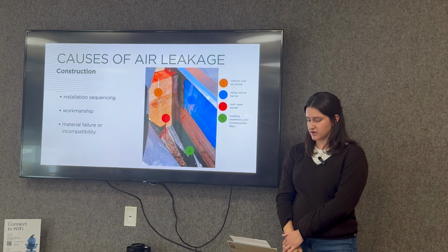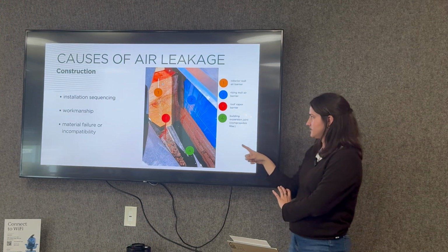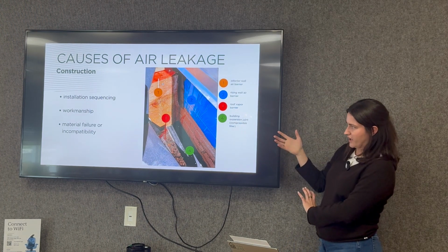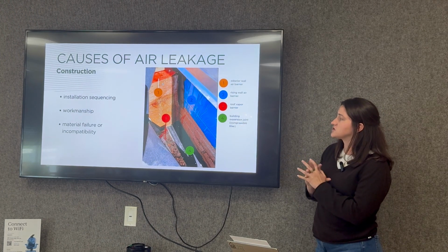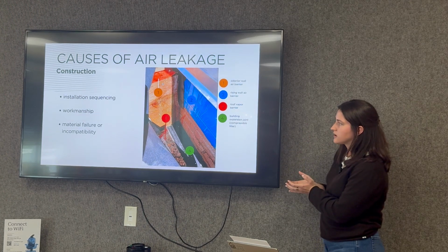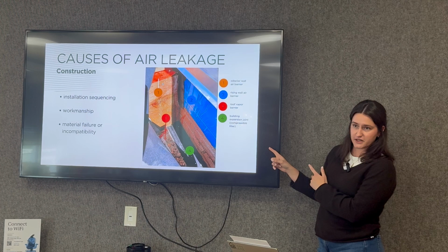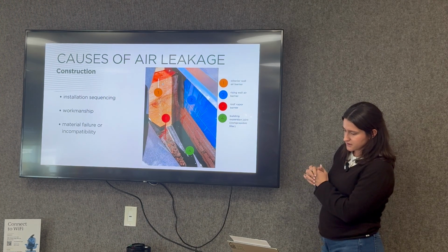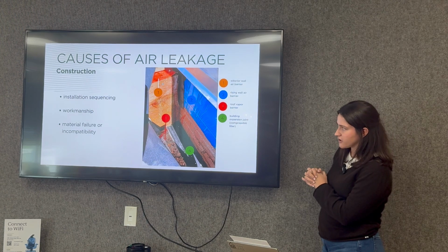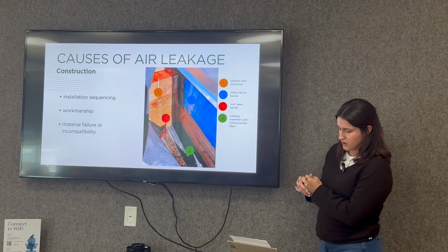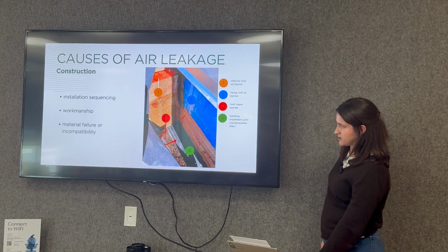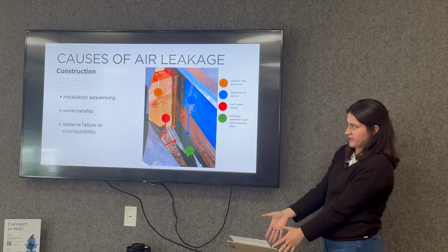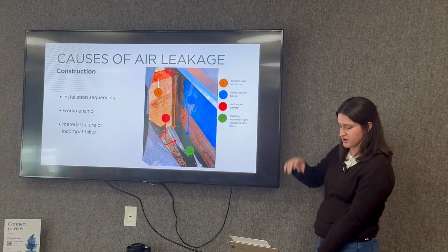So condensation is going to happen. It's going to be much more exacerbated if it's cold outside and you have a hot interior climate inside, like a natatorium. This would be detrimental there. And similarly, in a hot exterior climate, if you're really air conditioned inside, you might see the same sort of thing. So to correct this condition, the roof vapor barrier should have been extended horizontally to then die into the compressible filler, and the wall membranes too would have been brought down so that they terminated below where this compressible filler is to give us that air barrier continuity.